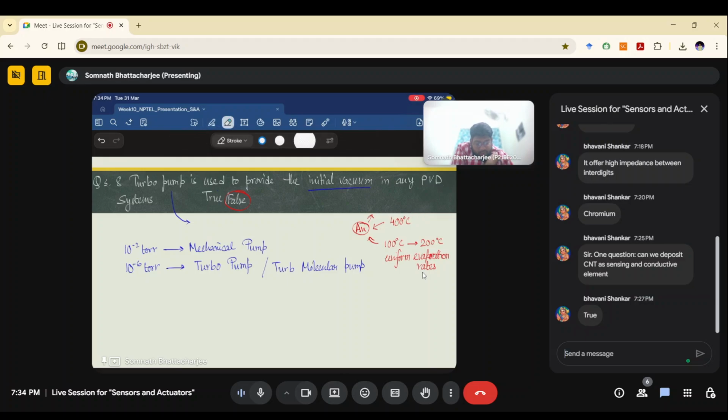No, in most of the systems we don't have a gradual thing. The turbo pump means we just turn it on and it starts to suck the air out. In our labs, I'm not sure about the other ones, the turbo pump goes directly to 10 to the minus 4 within, let's say, 4 to 5 seconds maximum, and then it increases gradually, because you are going towards 100 times less than this, so it takes more time. But the mechanical pump goes directly towards, let's say, 10 to the minus 1. That is very reasonable, and then it gradually decreases.